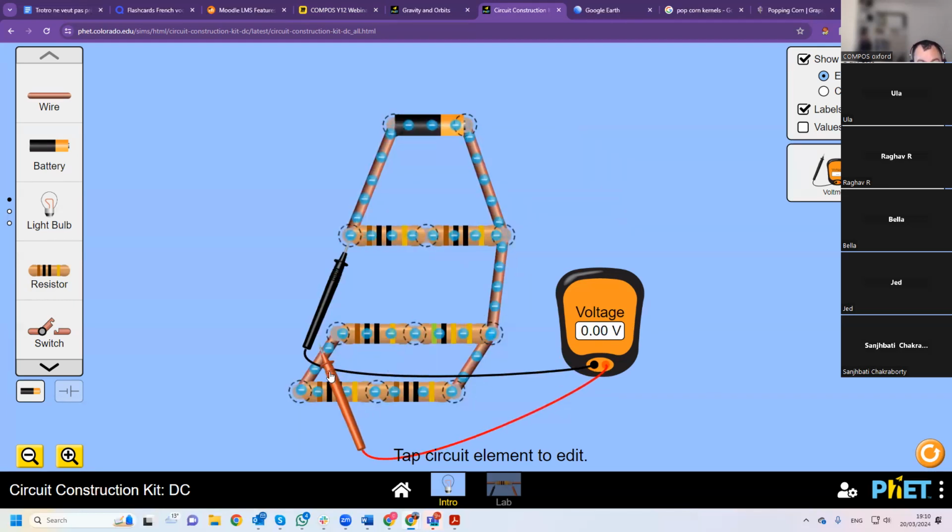In reality, the voltmeter would show 8, not 0. And adding a wire changes that to 0. So if adding a wire changes it, that means current would flow through the wire. If adding the wire doesn't change the voltage, then the current would not flow through the wire.